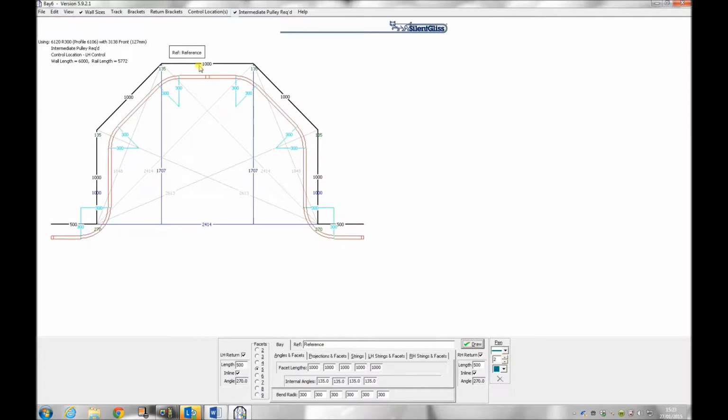You may have noticed the bend radius at the bottom of the input box. These are minimum radius defaults and it is not possible to bend to a lower radii. However, in some cases you may want to increase the radius of the bend to make a gradual curve from a multi-bend bay. The first and last inputs refer to the return bends radii, while the others represent the bay angles. As you change the radii, the bend will change shape to scale.